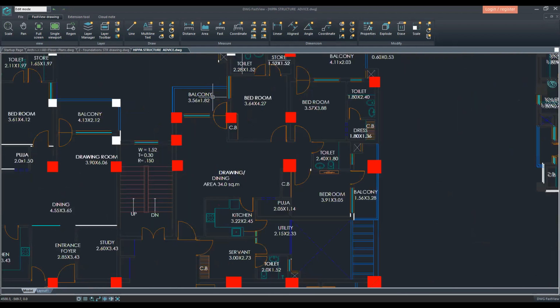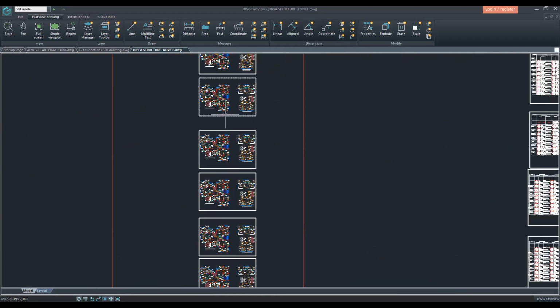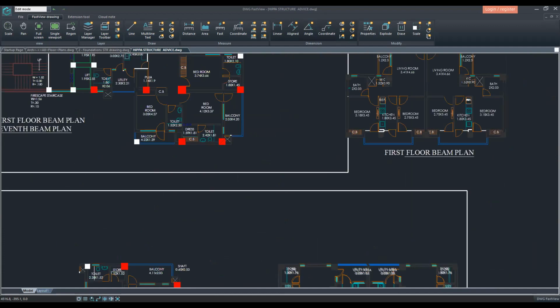So the architect will give you the input to fulfill the structure requirement. They will also advise you on where you have to place the columns. But see what will happen after this project is assigned to you. First we study this structure, and we will make changes in the structure. After that, we will make some center lines, that is the beam center line, like column placement or the arrangement of the grid.